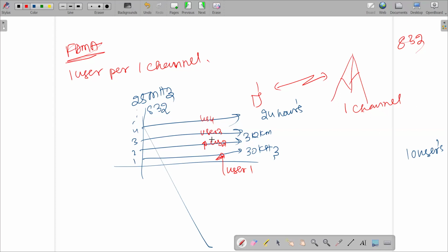Yes, sir. Hello? So the total frequency is divided, right? Frequency division multiple access. My frequency at 800 megahertz got divided into smaller sub channels, each of 30 kilohertz, assigned to each user.